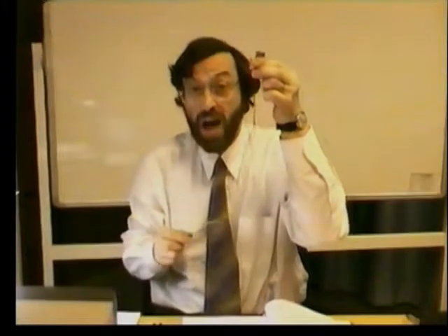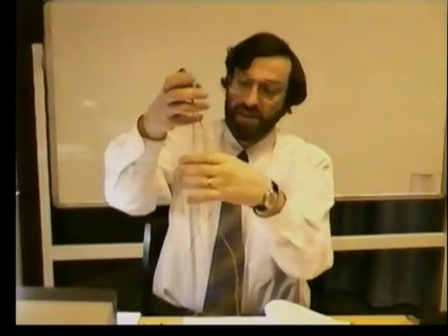Transmitters are special classes of transducers that have wires dangling out the back. So you have the ability both to measure and to transmit data. Traditionally, this is quite an old one, that's why I've got it. It was given to me as a free sample. They had 4 wires, 2 wires for the power and 2 wires for the transmitted signal.